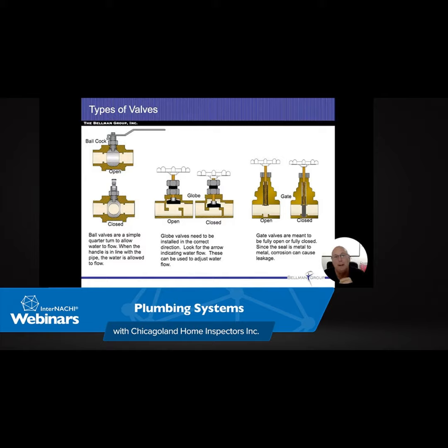Now here, you can see the cold water goes into one water heater, and then the hot water comes out of there and goes in through the dip tube into the second water heater, which goes ahead and feeds it to the house. So as I'm using the hot water from the left water heater, I'm actually replacing it with more hot water. So I'm going to get a longer lifespan out of it. And when I run out of hot water on the right water heater, now the cold water is going to start coming in there, but even that's going to be lukewarm. To me, it's just an easier, more verified way to use all the hot water.